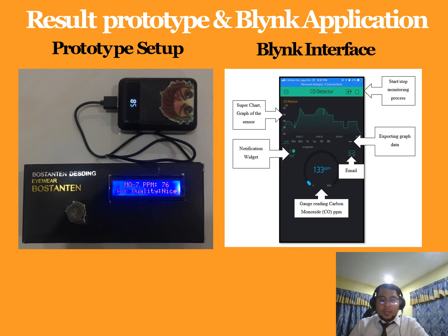The MQ7 and the NodeMCU are connected via pin A0, which is an analog pin. The LCD display that comes with an I2C chip was connected to D1 and D2. The SDA pin was connected to D1 and SCL was connected to D2.